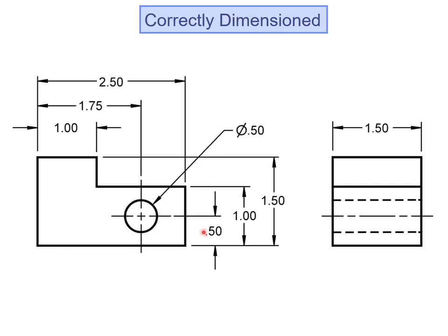Also, since we're dealing with inches, we don't put a 0 in front of the decimal point. If it was millimeters, then we would place a 0 in front of the decimal point. So by removing the 0, we're telling whoever's looking at the drawing that this is in inches. Again, we don't have the 0 in front of the decimal point. We have the diameter symbol, but not a 0 in front of the decimal point. So this is with any dimensions lower than 1. Drop the 0, and this is only .4 inches.